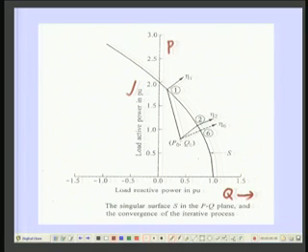Now, suppose you are operating initially at this point called P0Q0, the initial loading condition, and suppose you increase the load P and Q at random. Let us say you increase in this direction, so that you reach the surface S, or the curve S. This is called the surface S or curve S. Now, at this point the system becomes unstable. The question is, what is the shortest distance to instability?